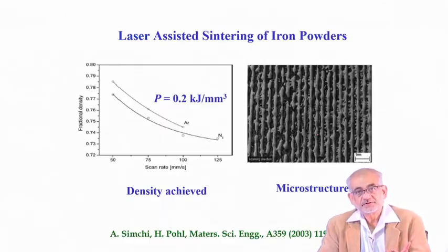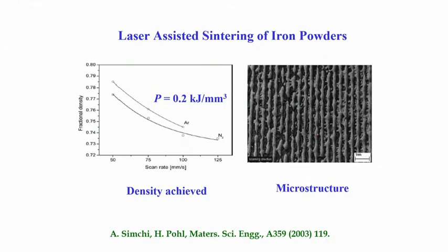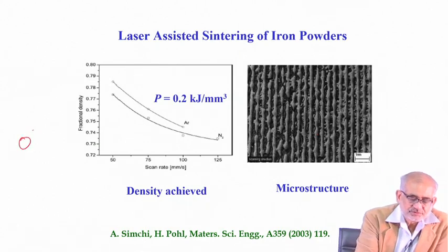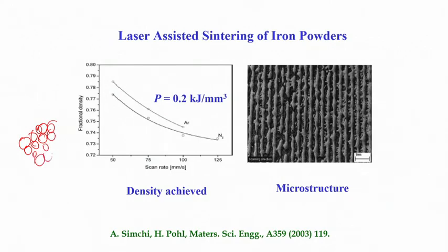Another form of material processing could be sintering. When you are dealing with powders or small objects, I mean particulates, you need to sinter them, join them together. Usually this could be powder masses of either similar size or various sizes, small or big, all kinds of possibilities. Joining will essentially depend upon creation of a temporary diffusion bond, so that electrons can flow across.